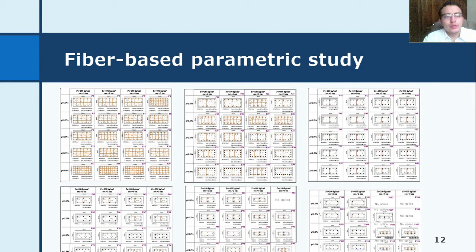For this purpose, a fiber-based parametric study was established for 120 column-type specimens that simulate boundary elements of special walls with different height-to-thickness ratios, and longitudinal steel ratios were combined with 2 cover thicknesses in order to propose a modification to the equation previously developed by Arrow.